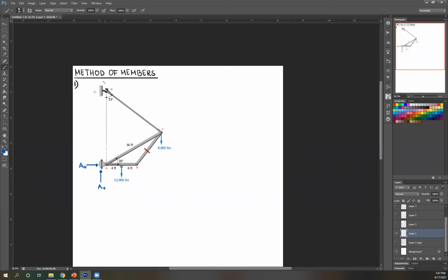Now, aside from that, you also have a support here, your hook supporting the cable. So what kind of reaction is there? This is a type of fixed support, so typically it also has vertical and horizontal reactions. But since this is just a cable, the reaction here is actually in the same direction as your cable. So it's this way, therefore it's also this way.